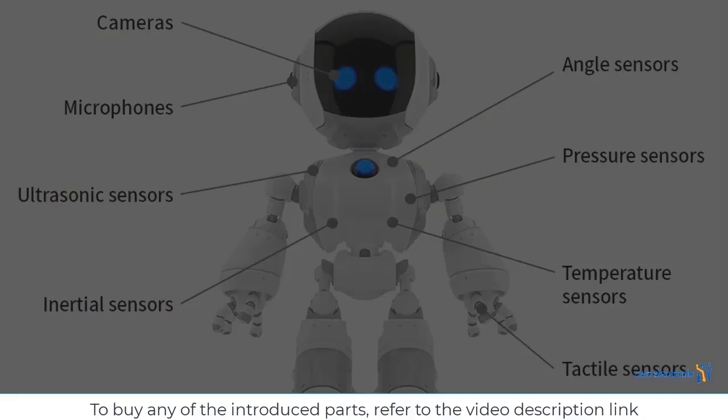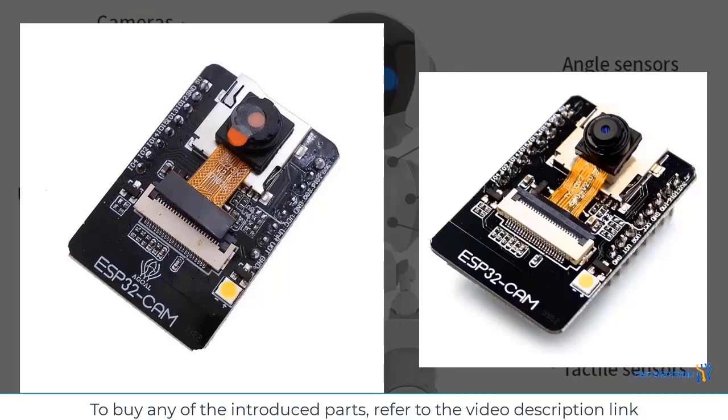It means that it is a very good and ideal camera that you can use normally in all kinds of robots. Another type of camera that even has a microcontroller on it for programming, which allows you to build an advanced robot, is a module called ESP-CAM, which is actually a combination of an ESP32 micro and a medium quality color camera placed together in a pack. And you can use this entire module as the main brain of the robot, which has pins that give different outputs. For example, you can make a robot that controls a number of motors because it gives outputs from these pins. You can connect these pins to a motor driver so that the robot is seeing and receiving the image of the environment and can move around easily.